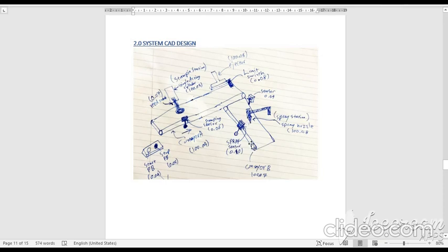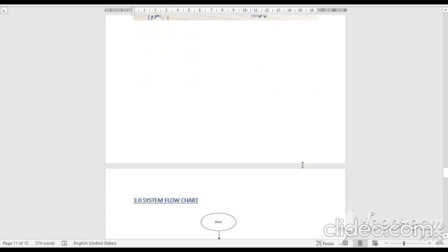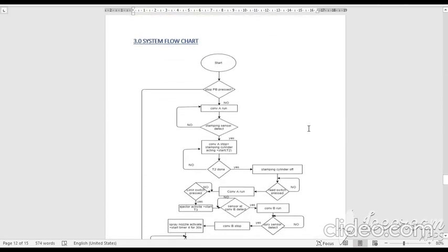After that the conveyor will stop, and we will have the spray station here, and the spray nozzle will be activated for 30 seconds, as we will explain later in the diagram. After that conveyor B will continue to work, with the condition that this conveyor will be continuously running during the program.